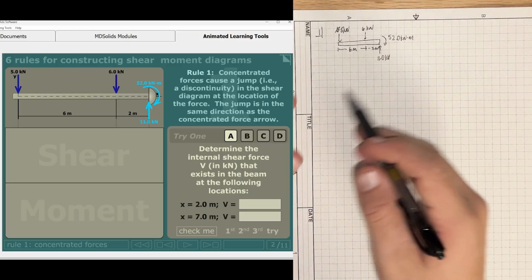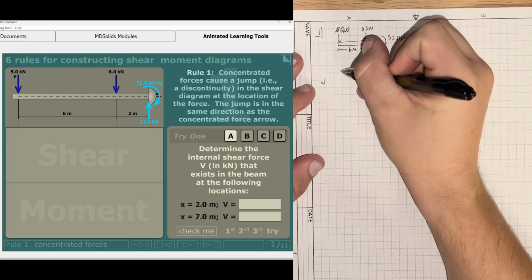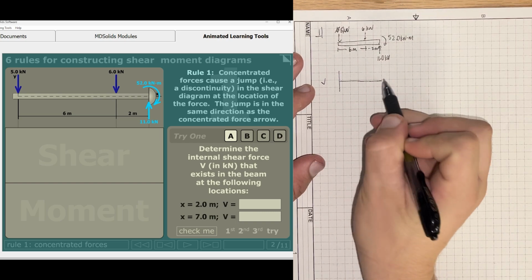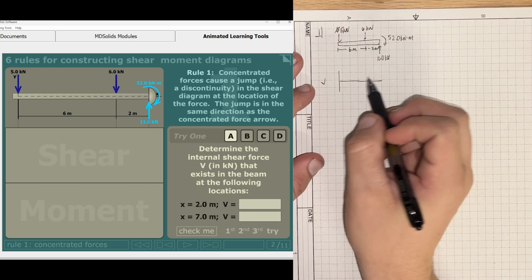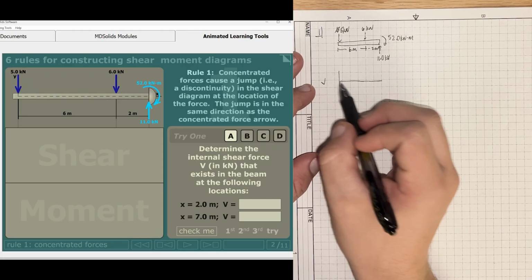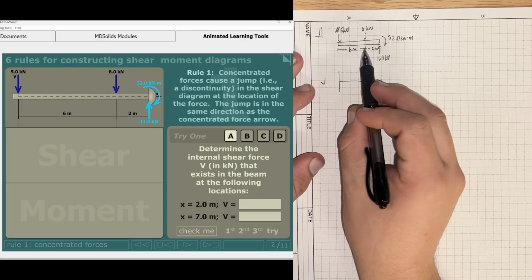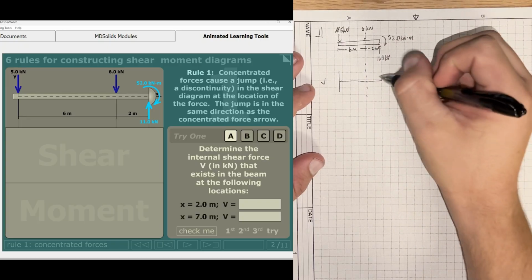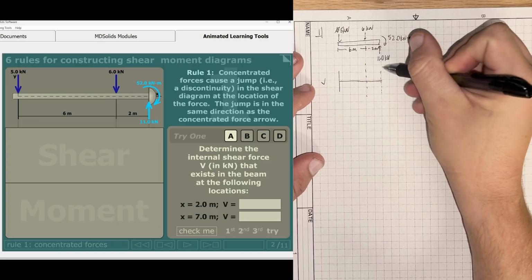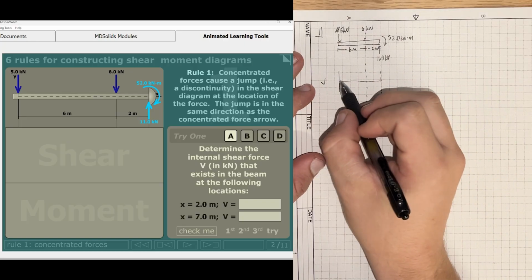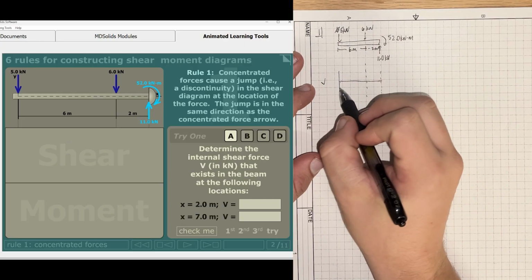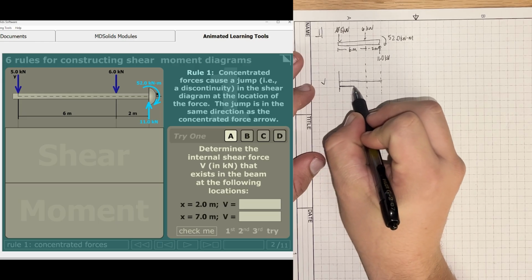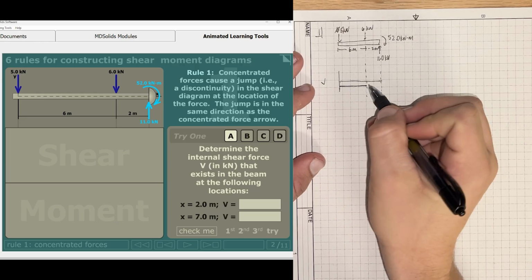It's just the shear. So what we can do is create our shear diagram here. This is an X and Y graph, where the Y-axis is the shear force and the X-axis is the distance that we've traveled. Right here, for instance, is 6 meters in, and right here is the actual end of our beam. In our shear diagram, we start at 0, then we pop down to -5 here. We can represent -5 as this, a horizontal line.